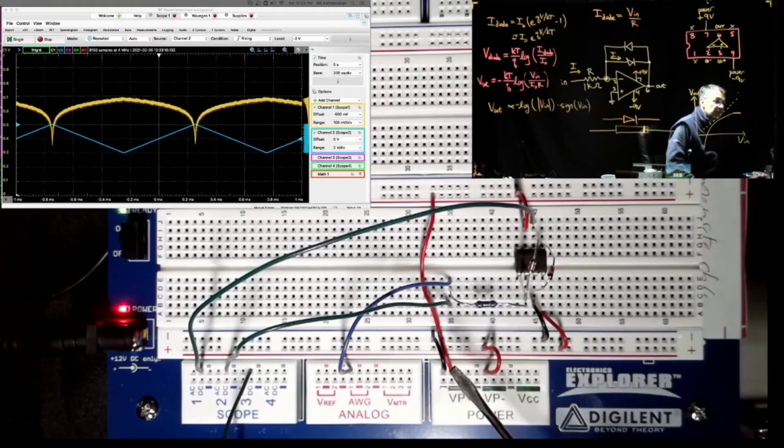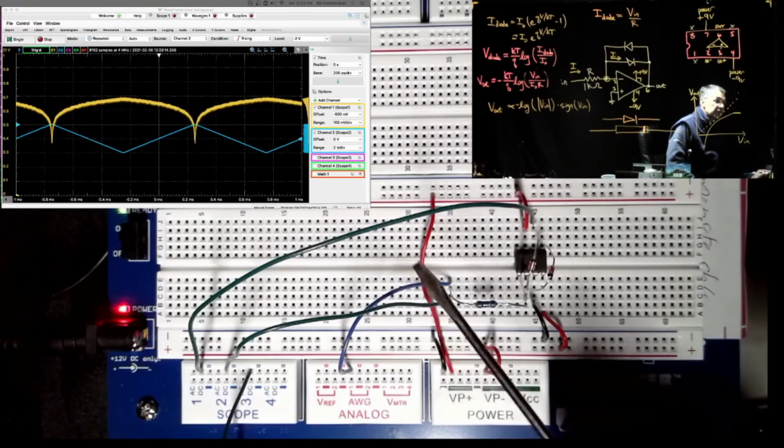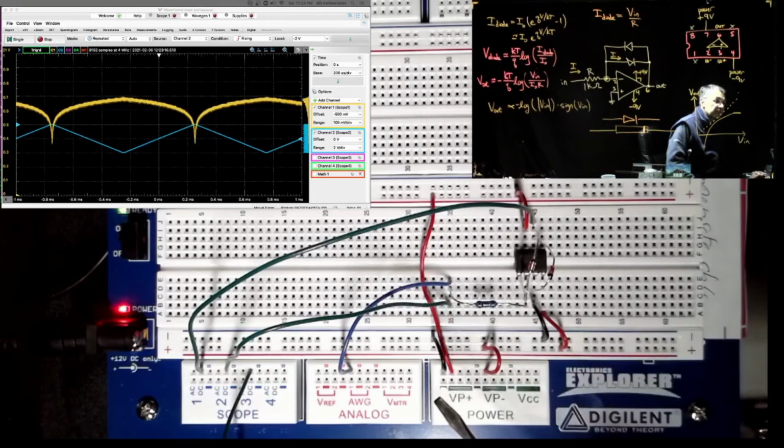And then it's a little awkward, but this long red wire is where the positive voltage is distributed from the power supply up to that top red bus. And then I'm using this little thing with the minus sign as a ground. So this black wire is basically distributing ground to the blue power bar on the bottom.